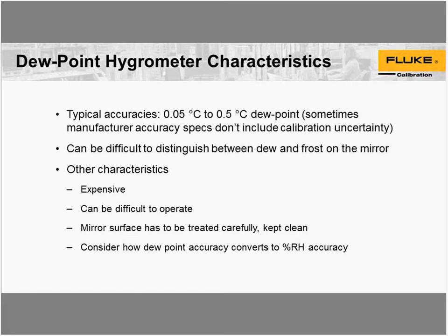One of the challenges of measuring the dew point is distinguishing between dew and frost on the mirror. One of the main challenges is that you have a nice clean mirror surface and you're running vapor over it, and those of you who know temperature, especially with fixed points, know that oftentimes materials don't freeze right at their prescribed freezing point.